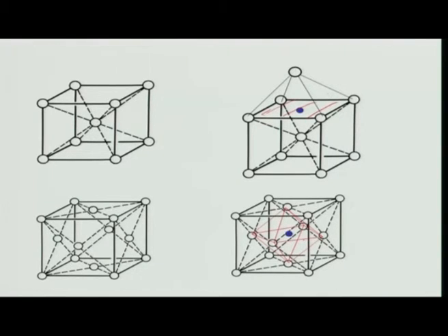How do you know tetrahedral voids? Very simple. I can generate tetrahedral and octahedral voids in many ways, but one of them requires that there has to be a tetrahedron. In an FCC unit cell, this is very easy to show. This is the FCC unit cell, suppose gamma iron. You can clearly see I can have a tetrahedron like this. Why is it a tetrahedron? Because it has 4 faces. So at the center of this tetrahedron I can put an atom because it has a void. This is known as a tetrahedral void.